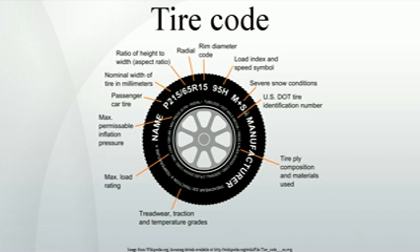Hence, a 195/55 R16 tire might alternatively be labeled 195/620 R16. Whilst this is theoretically ambiguous, in practice these two notations may easily be distinguished because the height of the side wall of an automotive tire is typically much less than the width.